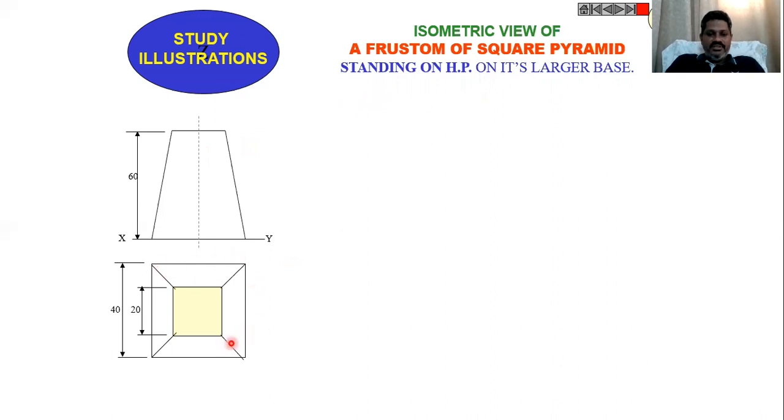That means the base shape is a square, and we are doing the section in such a way that the sectioned plane is parallel to the base. Then we call that a frustum of the square pyramid. Now the height is 60. On the top we will get a square of side 20, and at the bottom we have a square of side 40. These are the given dimensions.